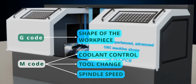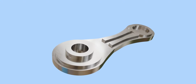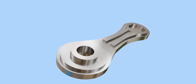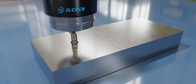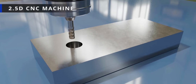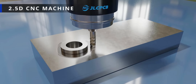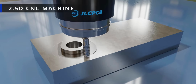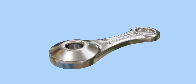Now comes the next machining challenge: how to machine this piece. Here, the depth of the machining varies, meaning that you must control the tool in the Z direction as well. You'll notice that when the tool moves in the Z direction, the X and Y movements are absent. This technique works for simple geometry. Such simplified machines with Z direction movement are known as 2.5D CNC machines.